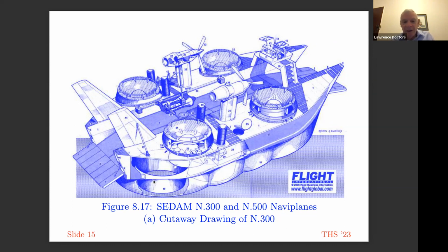There are 8 of them, as I just said, 4 on each side. So you can see the rear starboard jupe here. They're slightly tapered, so they're cone shaped, which means that it properly inflates. Early experiments were performed on changing the angle, experimenting with different angles of the cone. I've read somewhere that in some cases the angle was too shallow and the skirt didn't inflate properly.